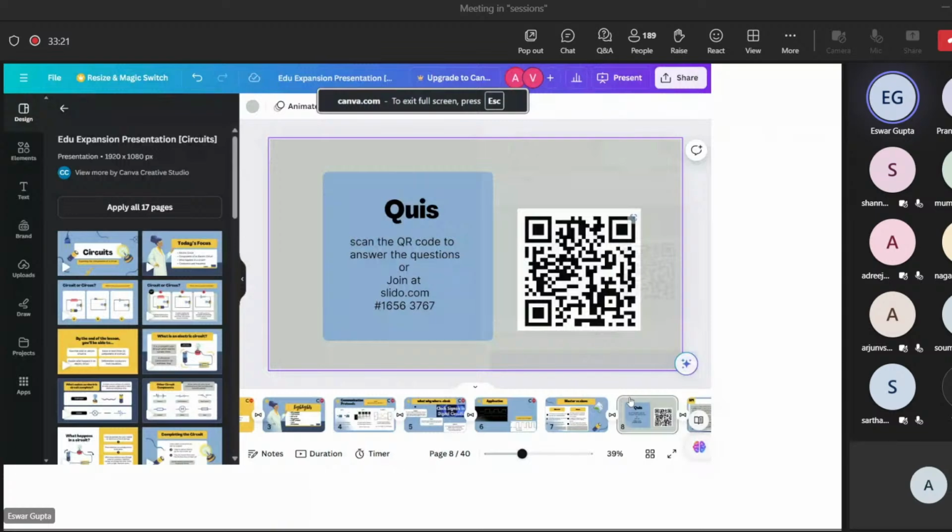So okay, it will just record and store the data. And it needs to transfer the data back to the master, right? Then it will use the second line, MISO. Master In, Slave Out. The master will get the data as input, and the slave will send the data as output. Okay. So here it is fine.